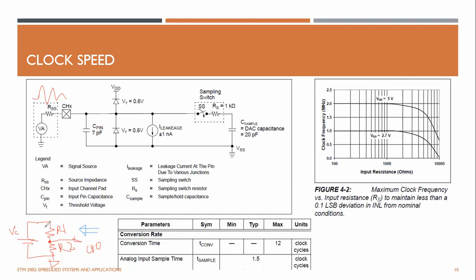For any AC signals, you can short circuit this voltage source, so that is equivalent to a parallel impedance, R1 parallel R2, shown at this point, and this voltage depends on the ratio. I'm talking about this simple example.